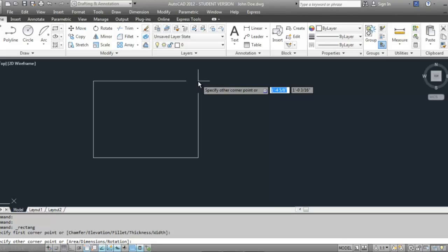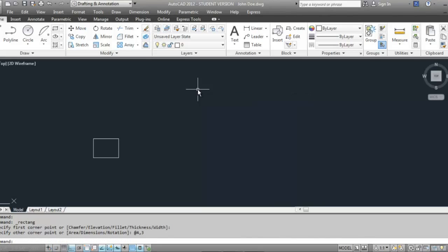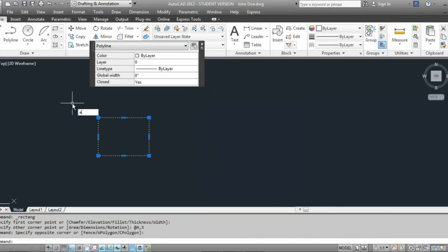So you're basically telling CAD the next point is @, and the @ symbol is the same @ symbol that you use for your Gmail or your email accounts, where you have your first name followed by last name @gmail.com. So you hold the shift key down and the numeral 2 and you get the @ symbol. You type the @ symbol and then you type the horizontal dimension first. Say you want it to be 4 inches, so you type 4, comma on the keyboard, and then 3, and hit enter. Okay, I'm going to do this one more time.